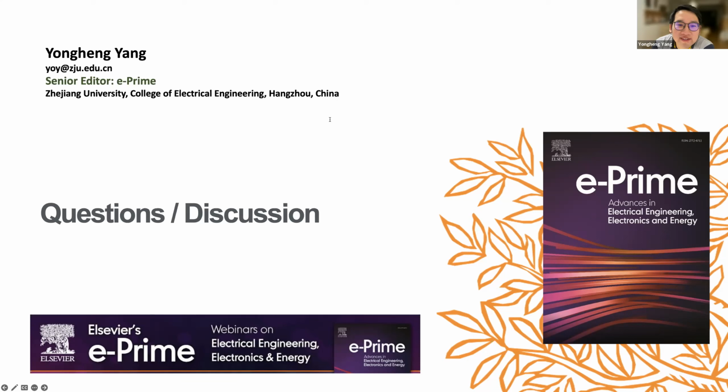Yeah, thanks a lot for the question. Of course, traditional topologies are standardized, they are modular, they have high modularity. So that's why the traditional topologies are used in renewables as well as in electric vehicles. But if you want to achieve the balance between the power density and the reliability, what you could do is have better thermal management systems in the power converters.